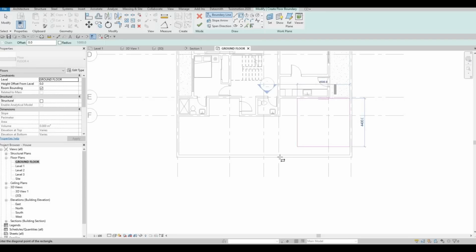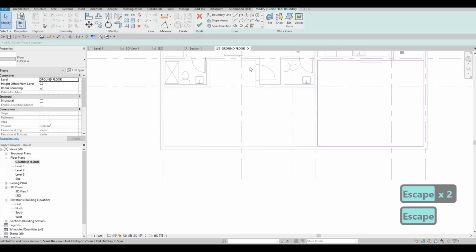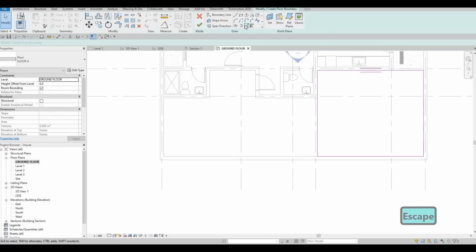We're going to have, for the carport right here, and then we could just select this one right here for the entrance, and then maybe right here as well. So I'm gonna drag this all the way here, trim and extend right here, and then right there.